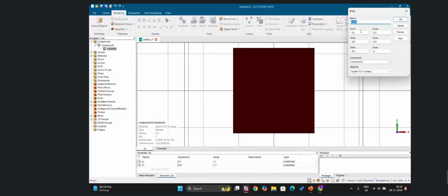In past years they have designed the FSS for ISM bands and for radar application. For ISM bands, as Sir said yesterday, he has chosen a very low frequency, that is 2.4 gigahertz, and also achieved a miniaturized size. So it is also applicable to this frequency, that is, we are going to design the band stop FSS for 50 gigahertz.